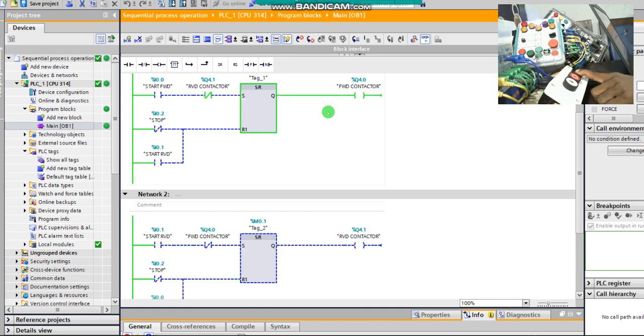If we are writing a program for a heavy induction motor, we need to introduce what we call a cool down duration by incorporating a timer into the system. So when you press this direction, before this one will come up, this one has to shut down before you initiate the command for this one to come up again. So in that case, we need to incorporate a timer system so that when this one is working,